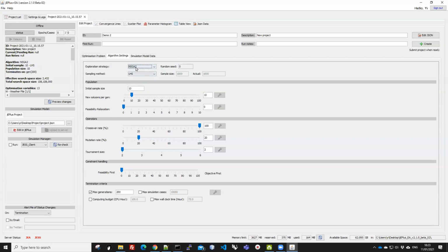So once you choose that, you're doing an optimization run. Because we have a very small problem, I will reduce the population size to make the thing run a little quicker. I'll explain what the population size is later. And we only want to run it up to, say, 50 generations. We don't want to run it for too long. So that's what I need to do to set the algorithm.